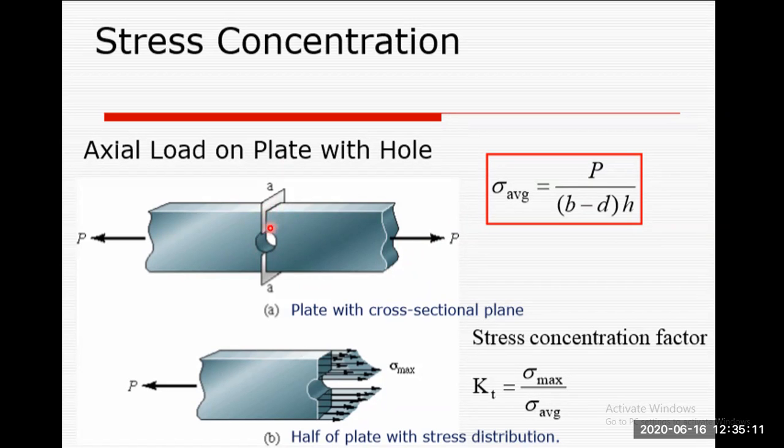So how this will fail is, you need to find exactly what is the cross sectional area. The exact cross section area of this part, for load P, is given by the breadth times the depth, with this subtracted by the diameter here. So B minus D is the breadth here, subtracted by this diameter. So the cross section area is just, you subtract the diameter and multiply with the height. That is the subtraction you do here. Why? Because only you want that particular area in the cross section.